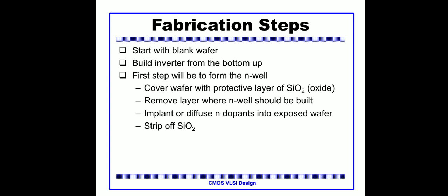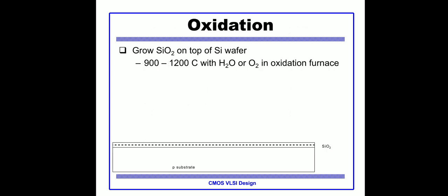The next one is the silicon dioxide layer. It is made of the material we call oxide. It has a stable structure. And the third one is the photoresist material, which is applied to the SiO2 layer. In oxidation, silicon dioxide grows on top of the silicon wafer, and the silicon dioxide is covered with the photoresist material. It is a light sensitive material which forms a coating over the surface.